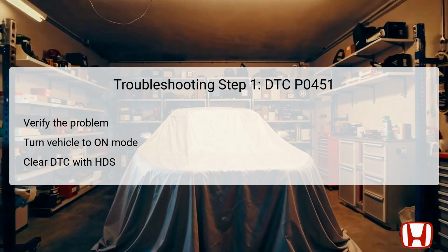Initializing the troubleshooting process begins with verifying the problem related to DTC P0451. First, turn the vehicle ignition to the on mode, which powers the vehicle's electrical systems without starting the engine. This allows for the necessary diagnostics to be performed.